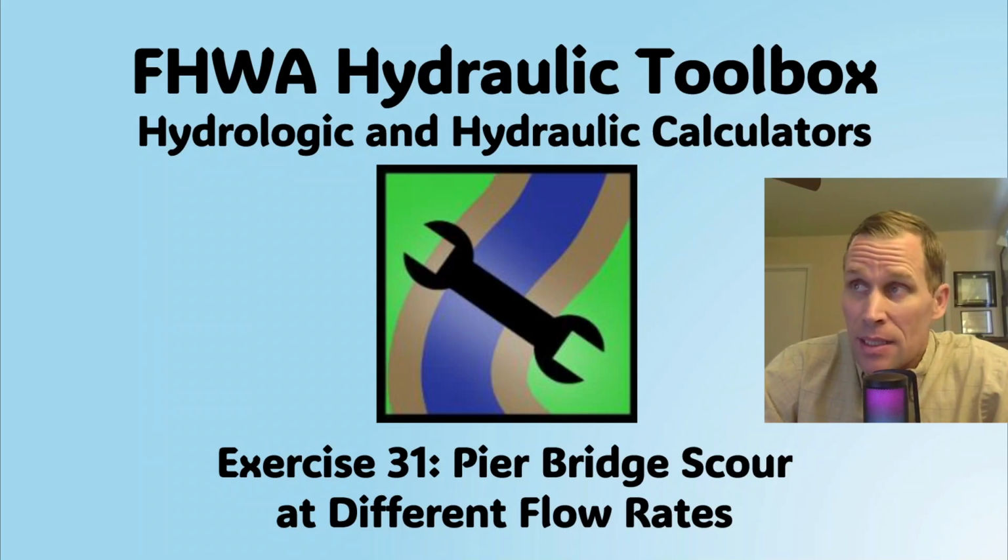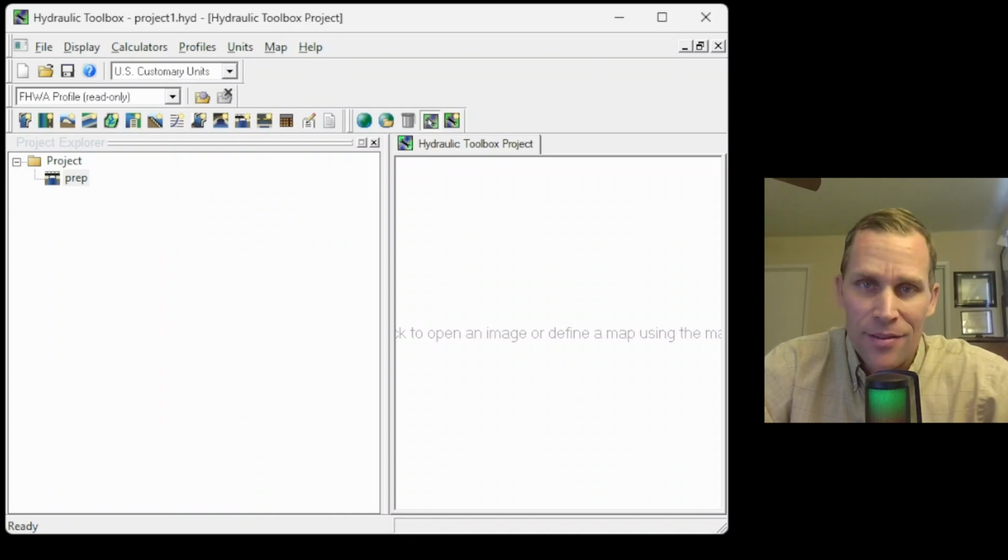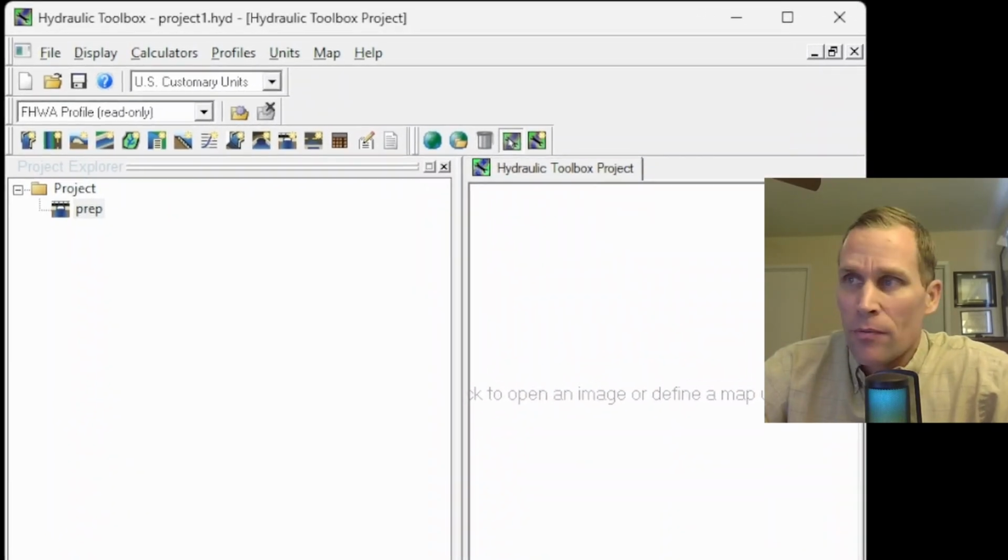This exercise is titled Pier Bridge Scour at Different Flow Rates. So what we're going to be investigating is the different amount of bridge scour at a pier that occurs at different flow rates. It will involve an FHWA project, which we need to set up first to define the geometry and the flow data. And then after that, we will use the bridge scour calculator right here in the hydraulic toolbox. Well, let's go ahead and get started with that first.